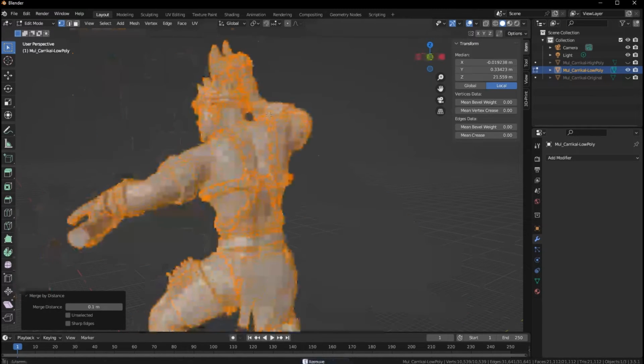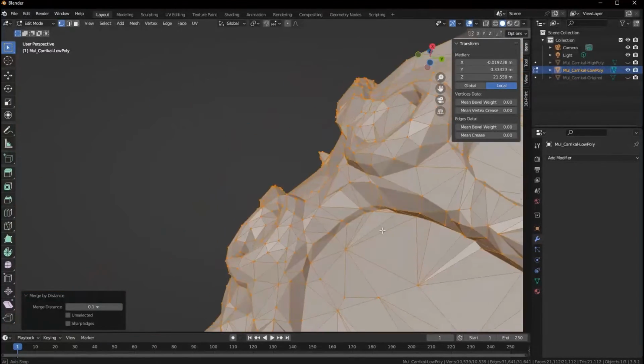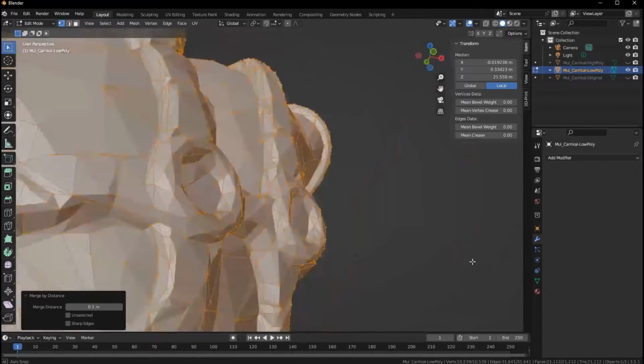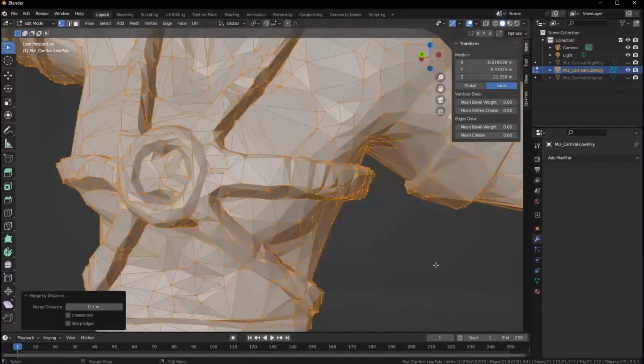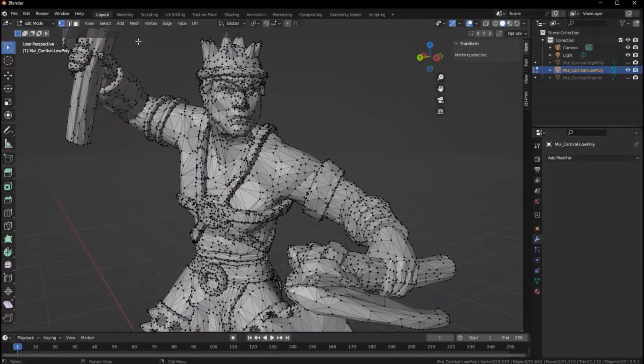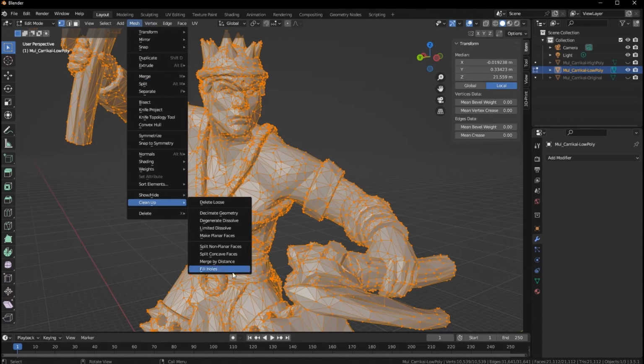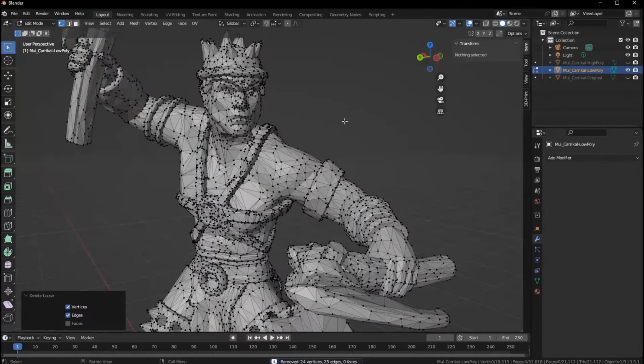It's going to remove 1,600 something vertices, but it removed them from spaces that had little tight packs. Now, I can look around and be like, oh man, did I take out something I wanted? I don't know, it looks pretty good. So we'll call it, and that's that cleanup. So what we've done is we did Mesh, Cleanup, Merge by Distance, we did Mesh, Cleanup, Delete Loose. I might just do another Delete Loose, because when we did that one cleanup, it created some other loose.